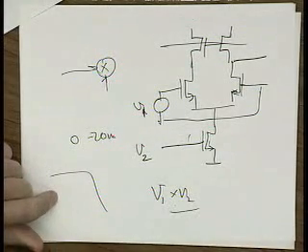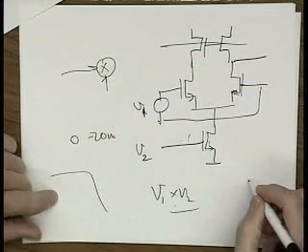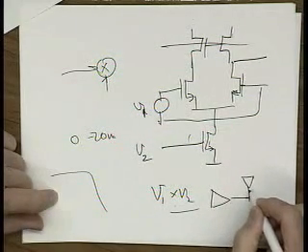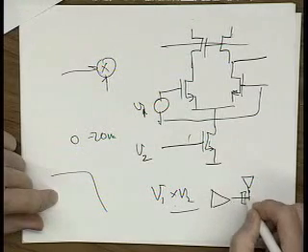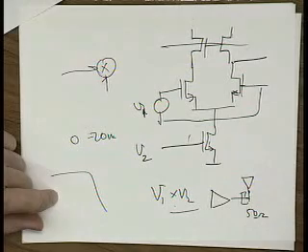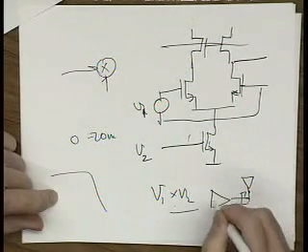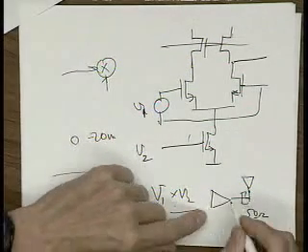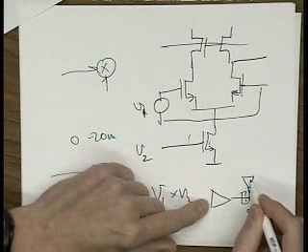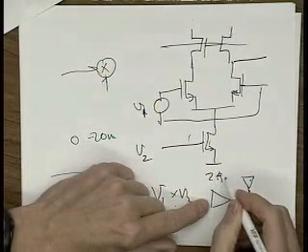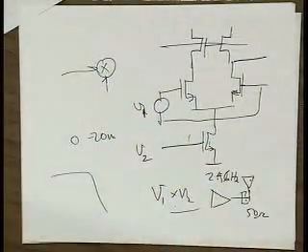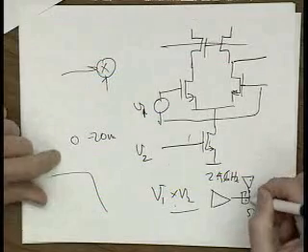Then there's the other big challenging circuit, the power amp driving the antenna. The antenna kind of looks like 50 ohms, so you know what this problem's all about. You had to do this in your first lecture, right? We mix back up to 2.4 gigahertz, and we have to have an amplifier which drives this antenna at 2.4 gigahertz or 5 gigahertz or 1.9 gigahertz, depending whether it's a cell phone or a Wi-Fi chip.